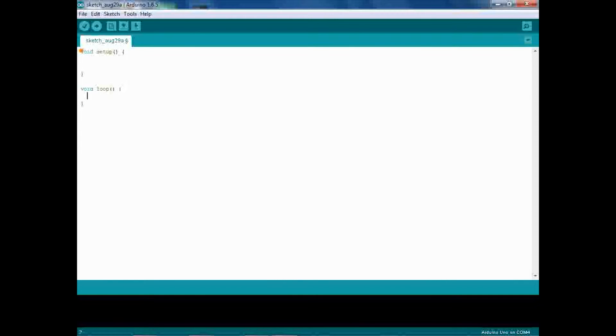In our interface project, we created variables. And in this program, we're going to create constants. Just like variables, constants will allow you to give a unique name to things that we write inside our program. In this case, we're giving a unique name to analog pin 0, and that will be our sensor pin.